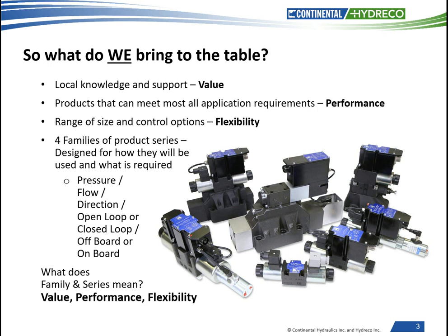So what do we bring to the table? We bring control. The use of proportional valves in a circuit allows you to accurately gain hydraulic variable control over a load. Once you have the control over the load, now you can make it do pretty much whatever you want, move faster and more accurately. But to gain this control, some things must also be sacrificed and then addressed.